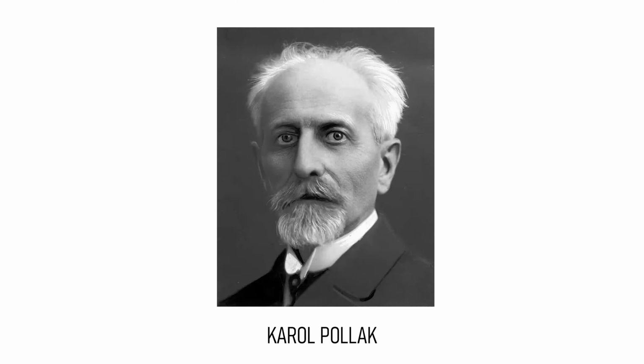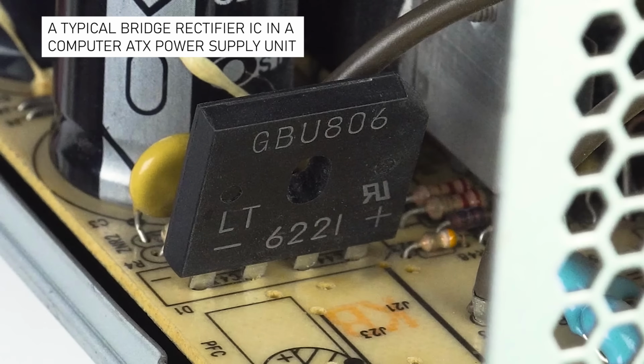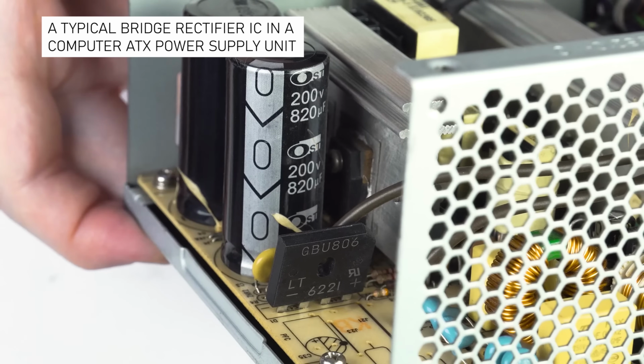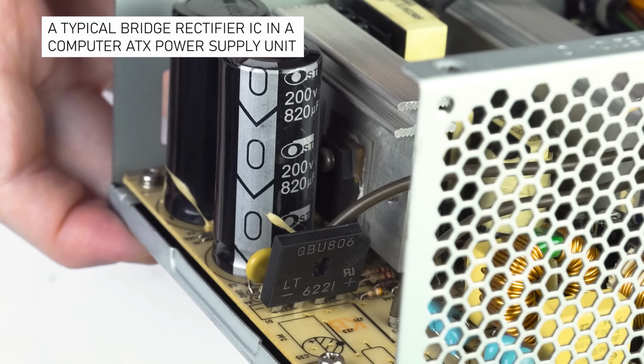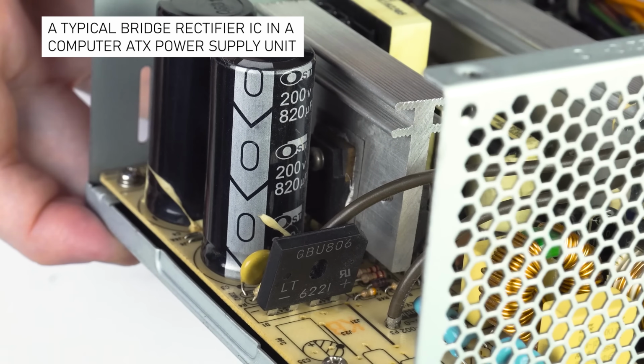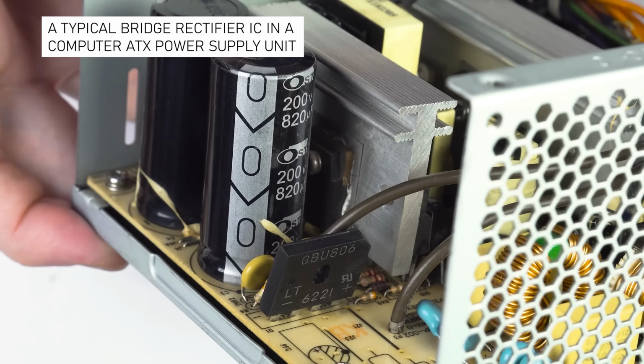These days, diode bridge is mostly manufactured as a dedicated module with 4 terminals, and as the bridge rectifier produces a pulsating DC voltage, in real circuits you will always see a capacitor wired in parallel to the output of the bridge. The purpose of the capacitor is to provide a smoother output voltage and prevent voltage spikes.